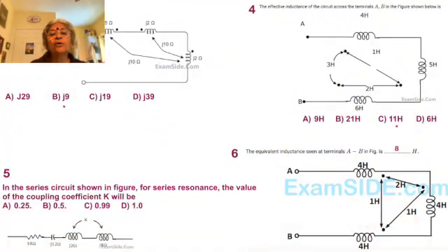Okay. Problem number 4. Here, of course, all the three coils have mutual inductances, unlike in problem 3, where we do not have mutual inductance between coil number 1 and 2. As before, the procedure is to add together the self inductances. So 4 and 5, 9 and 6, 15. And then coil 1, 2: it is entry at dotted and exit at dotted with respect to coil number 1 and 2, or 4 Henry and 5 Henry.